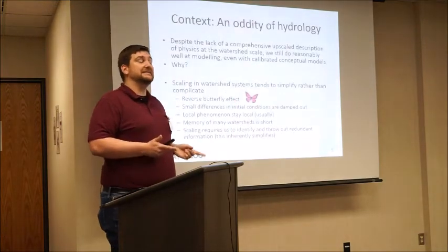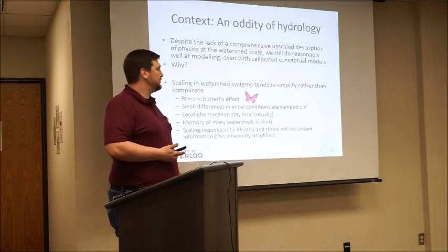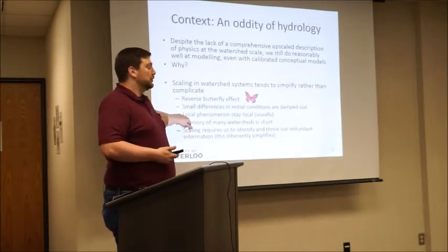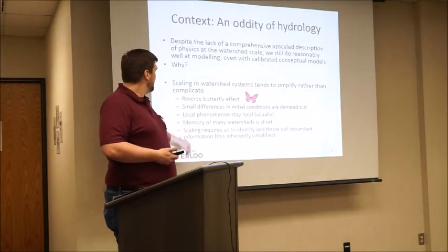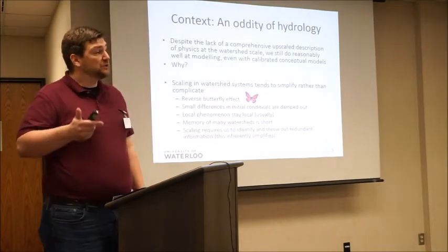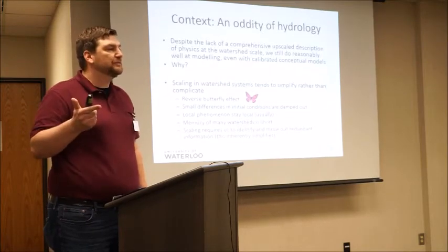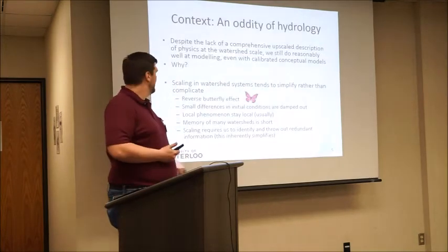Hydrology, in many cases, is the opposite. Those little details get smeared out, damped down. Small differences in initial conditions get petered out. Local phenomena are often only local, and they stay local. Watershed memories tend to be short. Again, not in all cases. This is why we treat watersheds as quasi-steady state. Every year they reboot. That's why we have a water year. Every October we can reboot our model.